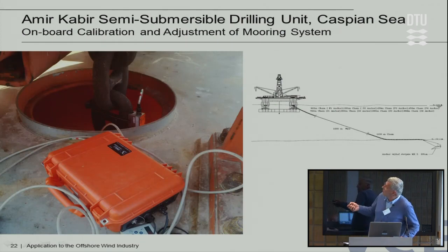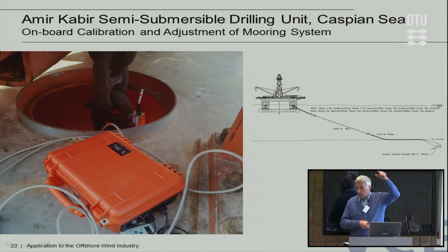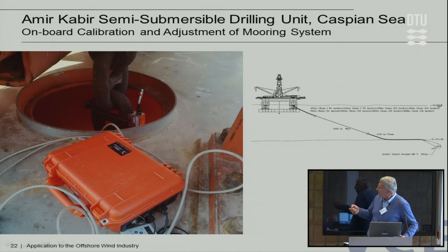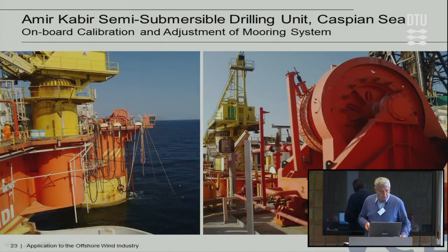It can be simply monitored like this with an accelerometer. This is the mooring chain here, and it goes on roll on top and roll on bottom, so you have a clear distance between 2 points, and you can quickly measure what the load on this chain is. It's 4 kilometers long, for example, in a 700-meter deep sea. Here we don't have this very strict confidentiality thing. This is how it looks in practice.